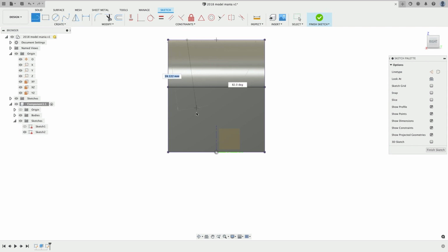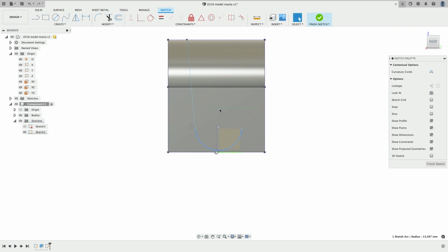which is now usable for sketch connections and constraints. I sketch a line. I'm just kind of making it up as I go where it's going to be. And then I click and drag with my left click, and that creates a tangent arc. It's a nice little shortcut. And if it's driving you crazy, just delete it and go up to arc and sketch that arc.